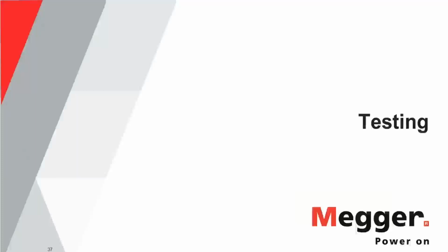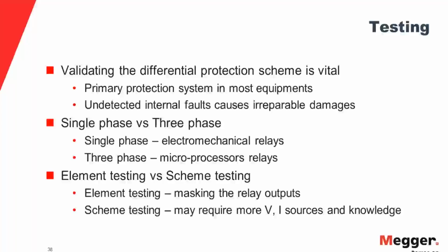In the motor differential, the CTs will pretty much have the same ratio and same type in order to prevent the mismatch. But we did cover completely the CT mismatches and the other challenges faced for a generator differential, which can be applicable for the motor differential as well.